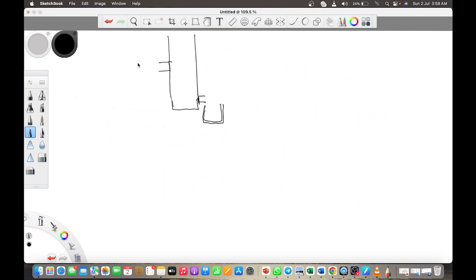So first thing, you press a switch. Let's call the switch S3, right? When you press the switch S3, it opens this valve. The valve V1 opens, and it starts filling with the fluid. So it keeps filling until the fluid gets to this level here, right? So there must be a sensor that will sense the level.